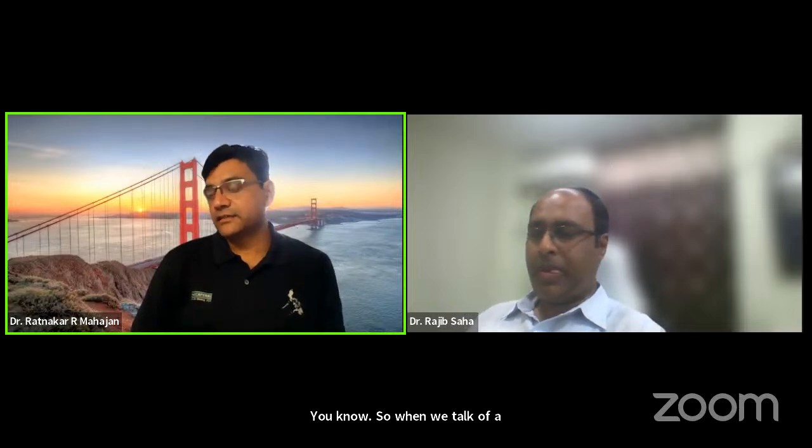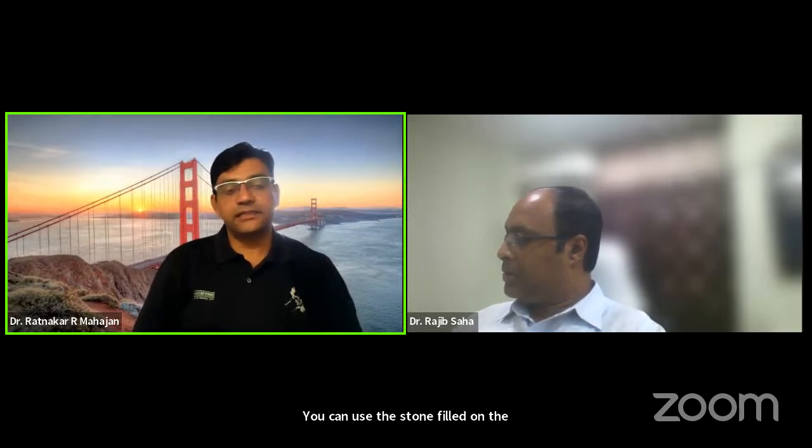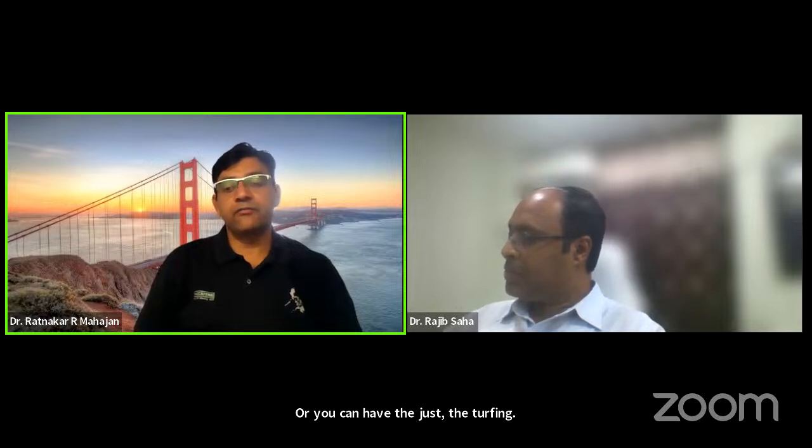Yeah, sure. So there are various bioengineering techniques, and when we say slope protection, I assume it's about soil erosion. When we talk of soil erosion, there are very good techniques available, like you can use rolled erosion control products made up of jute or coir or synthetic mats. You can use stone-filled mattresses on the slopes, or you can have just turfing or sodding, or even mulching.